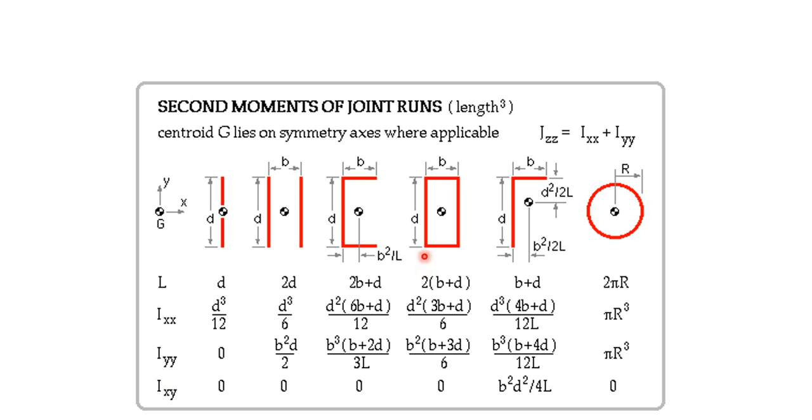Here these expressions can be used directly for calculating I and G, but I personally feel we should not use these equations, because sometimes they may not be available. These formulas may not be available in the examination, or you may confuse some expression. It's better to use the basic principle of calculating IXX, IYY and J for the problems.